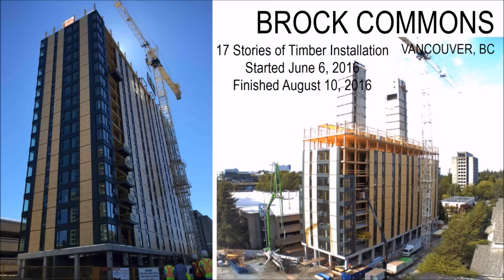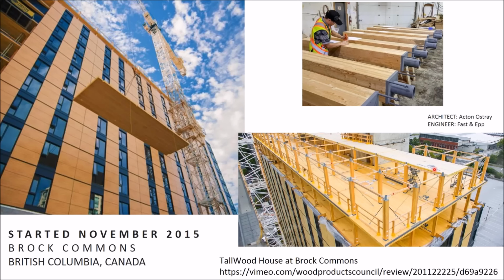What is actually interesting from our structural gravity load perspective is that it uses a two-way floor deck, meaning that it uses the CLT to span in both the long direction and the short direction of the panel and have that supported just on columns at the corners and interior points of those panels. These other little framing members you see here between the columns are really just spacers that were taken down after the CLT panels were put into place. So this is really using that two-way spanning capability to create a beamless floor system. It's an interesting idea.